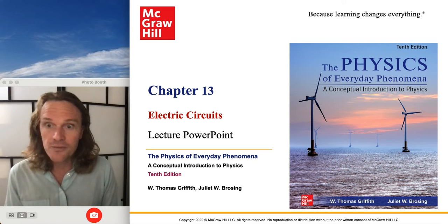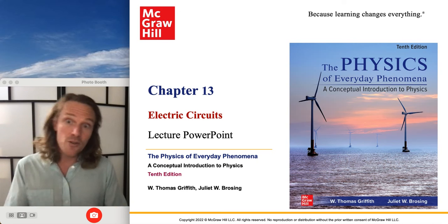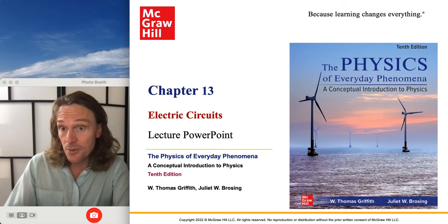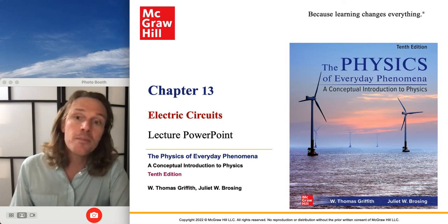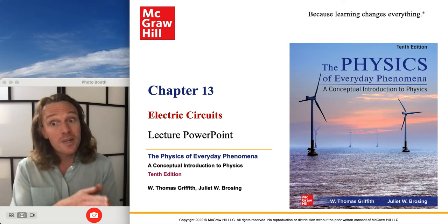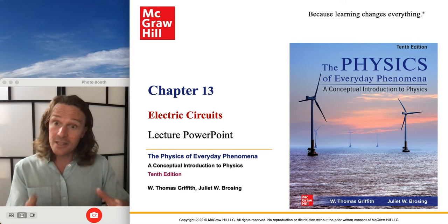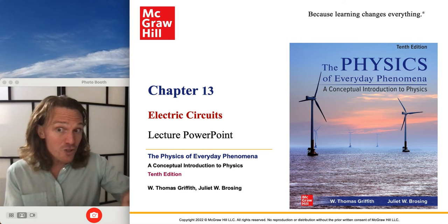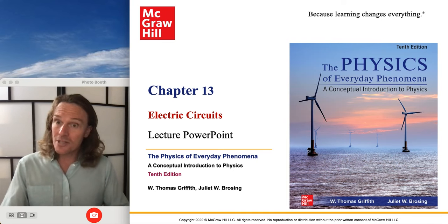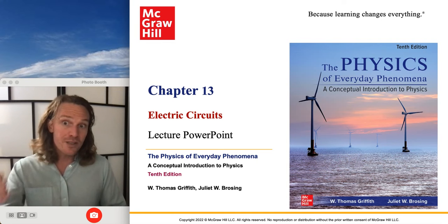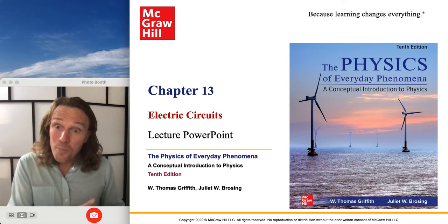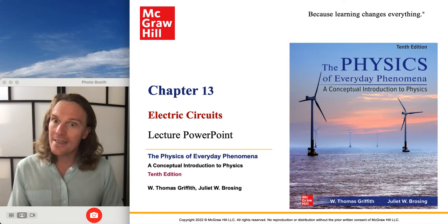Okay, they'll bump into each other and bump into the fixed atomic nuclei within the metal and so on. But it's like they all got tipped to the side and they all want to move in that direction. If we go to the analogy of a fluid, in this case a fluid of electrons, tiny little balls, right? Trillions upon trillions of them, rolling in one direction, the downhill direction, which is the direction of the electric field. Okay, although be careful, because the electric field was built on the convention, which turned out to be wrong, that positive charges are the charges that are free to move. But it's not. Metals are the most common conductor, and when metals conduct, they conduct free electrons. That means that when you look at the direction of the field and the direction of current, this term that we're getting into in this chapter, it all points the other way, which is to say it points the way that electrons aren't moving.